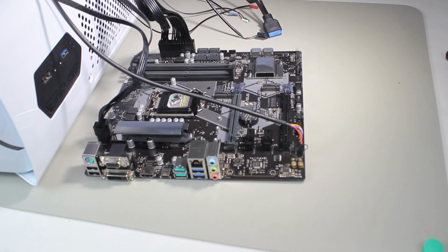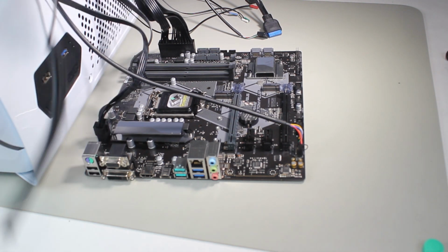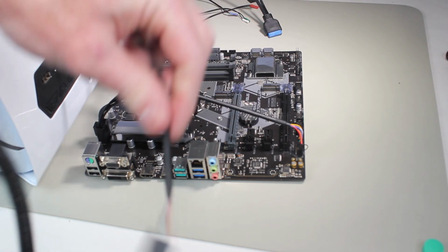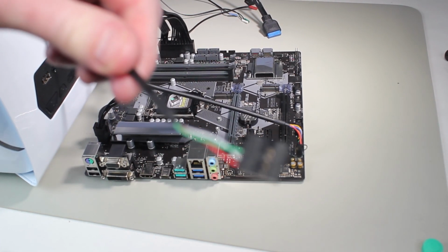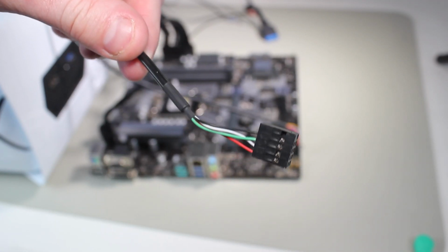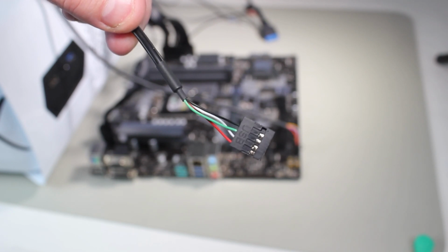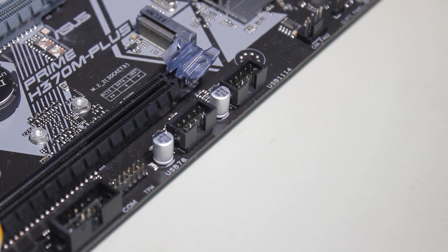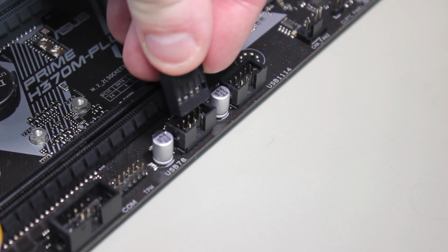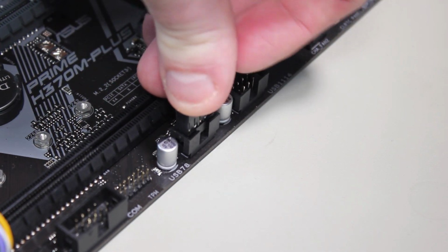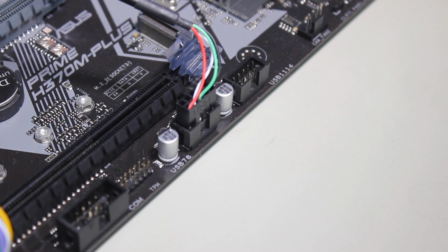This computer case has a USB 2 and a USB 3 connector. I will first locate the USB 2 connector. You will notice that it is a small connector. The connector is black, while USB 3 connectors are usually blue and have more pins. Like the audio connector, it is just a matter of plugging the connector into the motherboard. Your motherboard may have multiple USB plugs, so it is just a matter of choosing one as they all perform the same function.